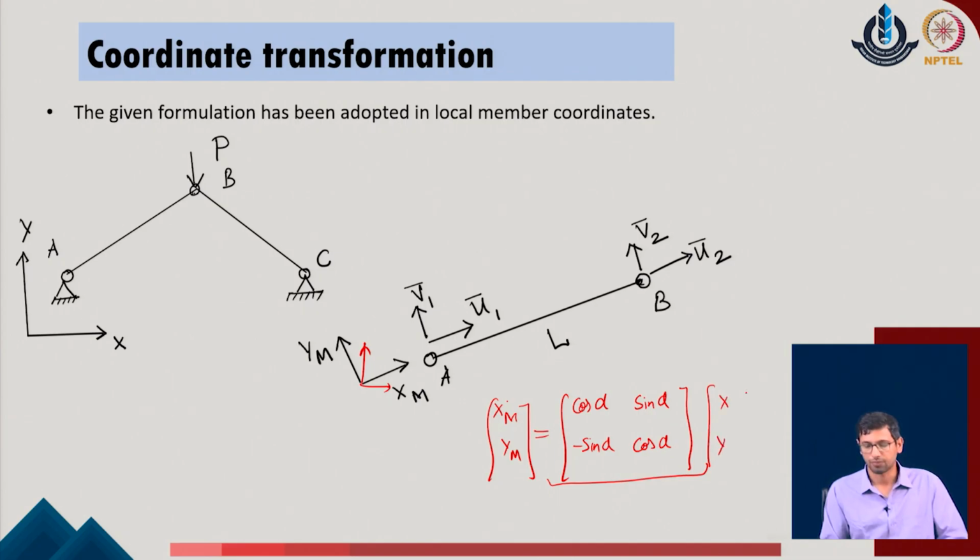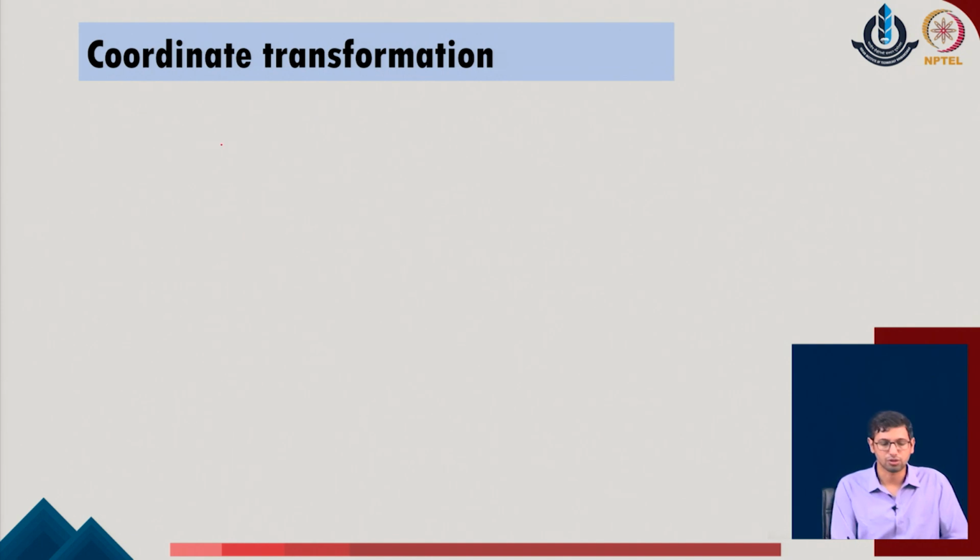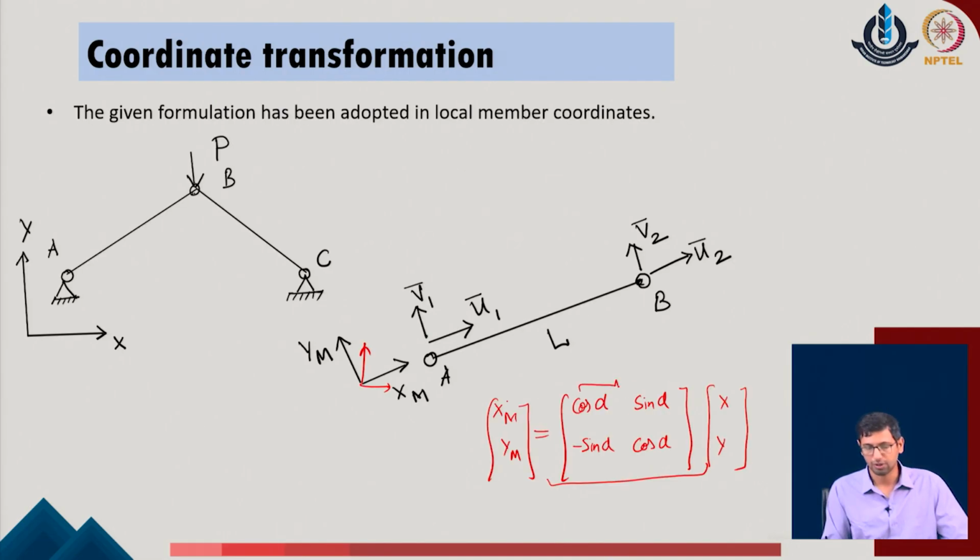And now, using a similar idea, we can modify the overall stiffness of the system. The kT bar, which is defined in the local member coordinates, can also be modified in terms of the overall structural system, or the general kT expression, by considering that this parameter is the rotation matrix R in the given problem.